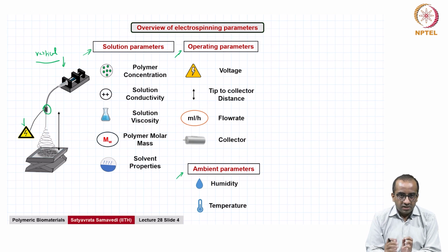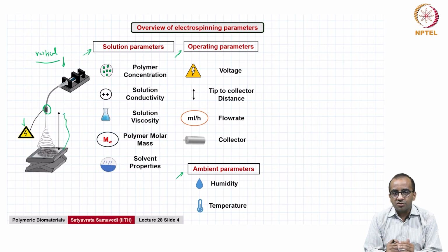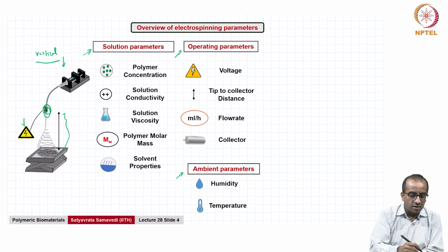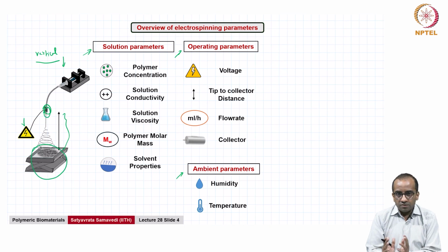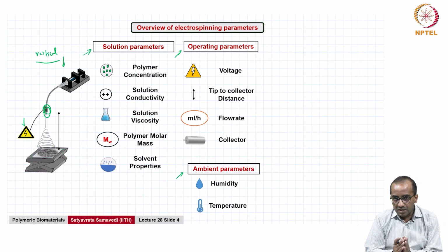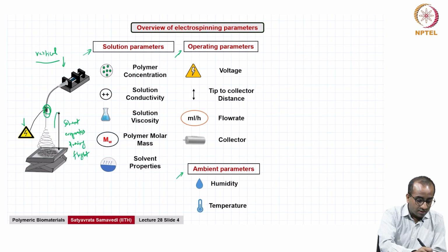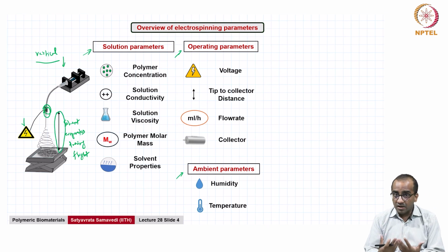One of the key things to keep in mind in electrospinning, if you're talking about solution electrospinning particularly, is there is a requirement to have a separation distance between the tip of the needle and the collector. And this does a lot of things, but one of the primary things it achieves is it gives the polymer solution the time to completely evaporate the solvent. So, the solvent evaporates during flight, right, over this distance, and a lot of the drying and thinning happens.